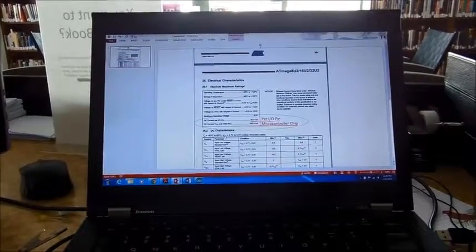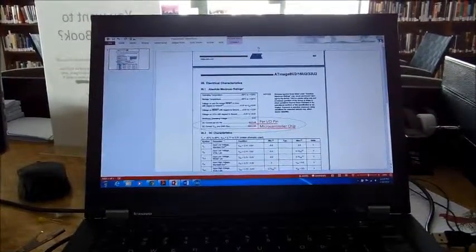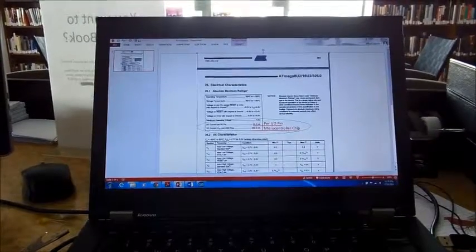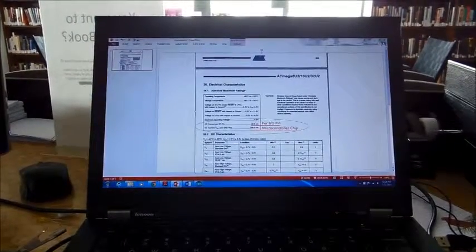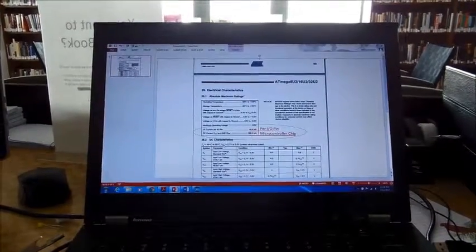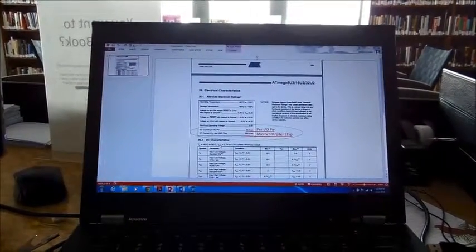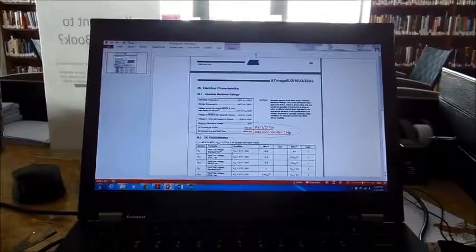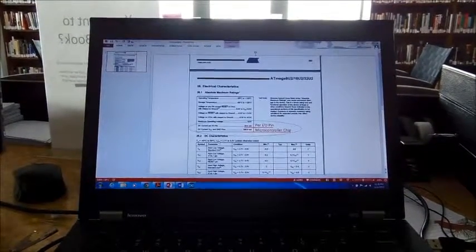And here you can see that it's pretty clear the absolute maximum per I/O pin is 40 mA, and for the whole chip it's 200 mA. So you certainly can't be running a whole bunch of them at 40 mA. But anyway,